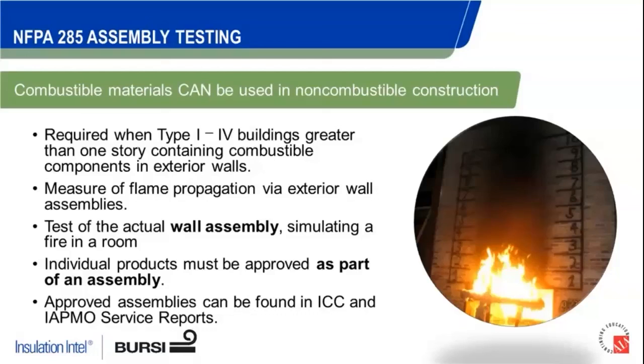So the bottom line is, if we want to use that material in a non-combustible building type, we have to do a fire test to prove that the wall system will hold up under flame exposure for an extended period of time to allow for egress.